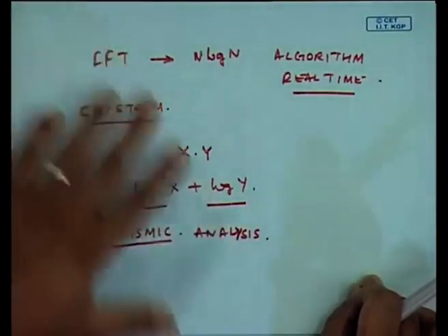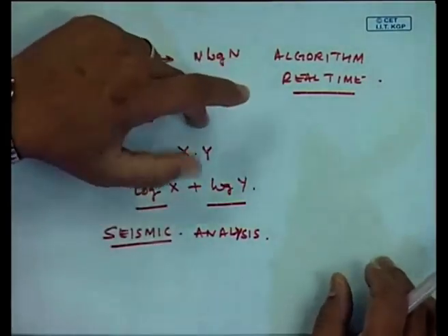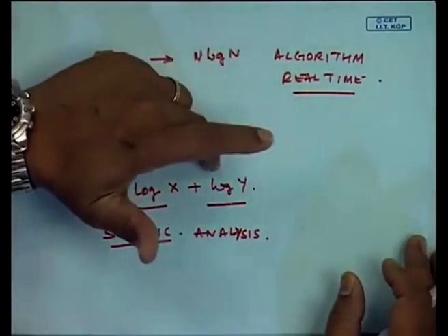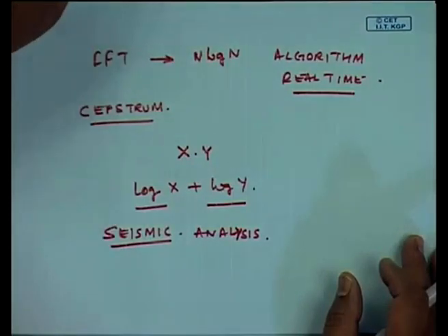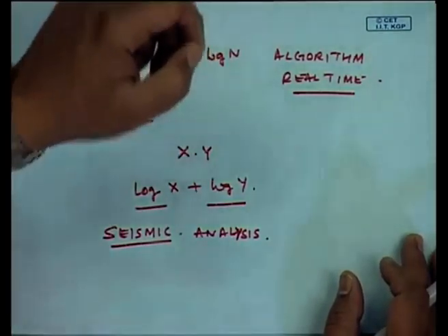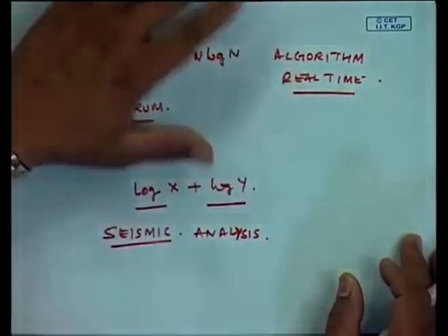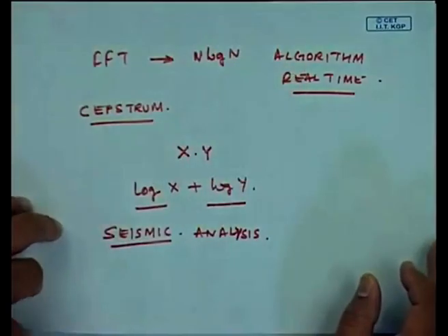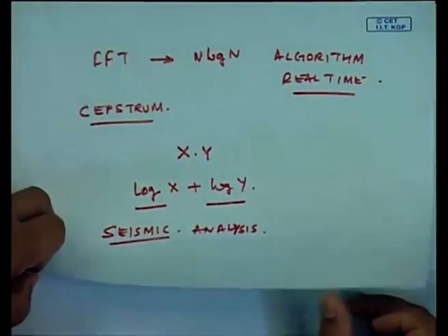That is another advantage of Cepstrum analysis, but here we will see the same also happens. Suppose I have a large gearbox, a lot of signal contamination occurs because of the path, whether it is coming through bearing A or through bearing A, B, C, all those effects will be lost or easily removed once we do Cepstrum. So, to summarize, Cepstrum is a powerful method to find out sidebands in modulated signals.